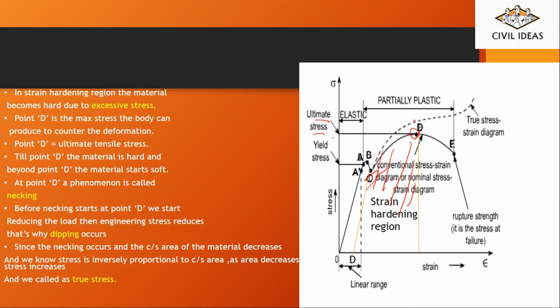Since necking occurs, the cross-sectional area of the material decreases, and we know stress is inversely proportional to the cross-sectional area. As area decreases, the stress automatically will increase.